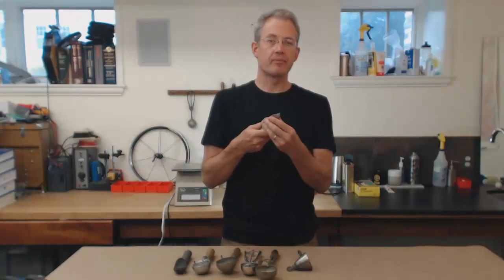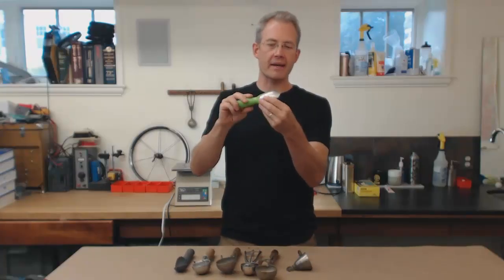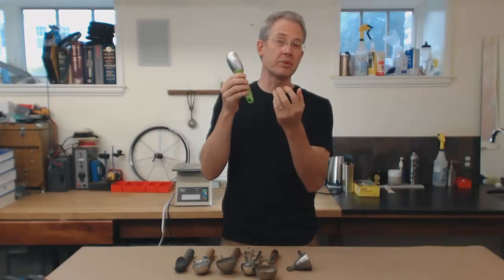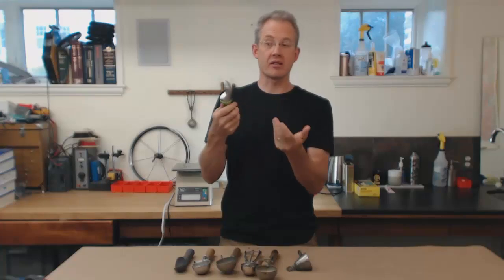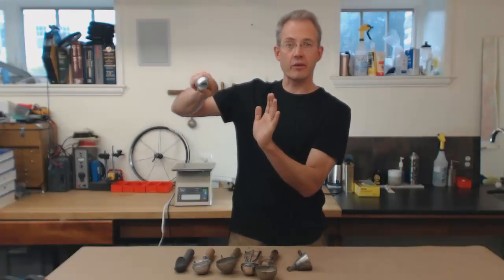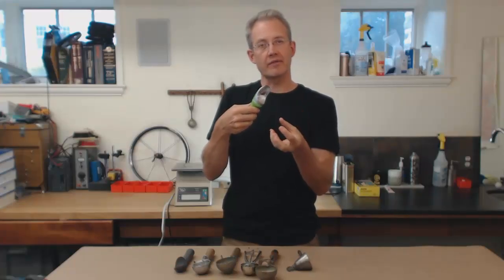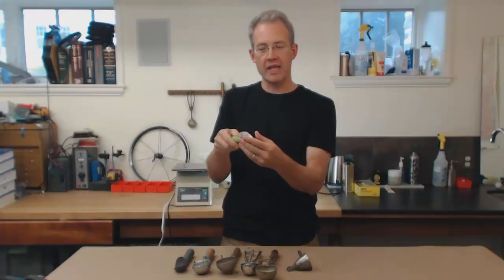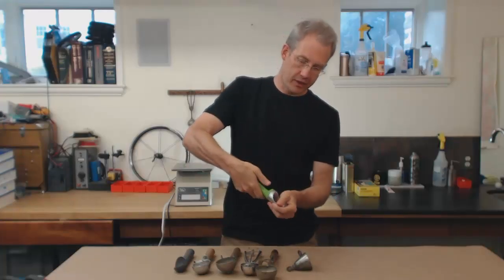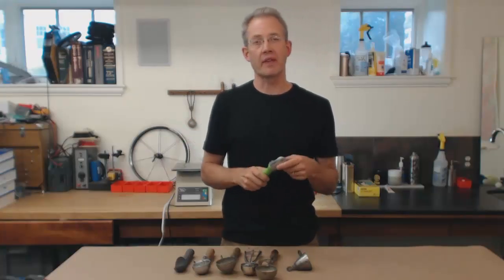The Xylus design in many ways builds on the success of this approach. It uses the large thermal mass of this aluminum head to reliably stay warmer than the ice cream, as long as it isn't stored in the freezer, and still uses that curved surface to create a curl of ice cream, but then the warmth of this head allows the ice cream to separate from the curved mold of the head itself. It also has a very ergonomic grip, which allows the operator's thumb to apply a downward force, which relieves some of the stress on the wrist.